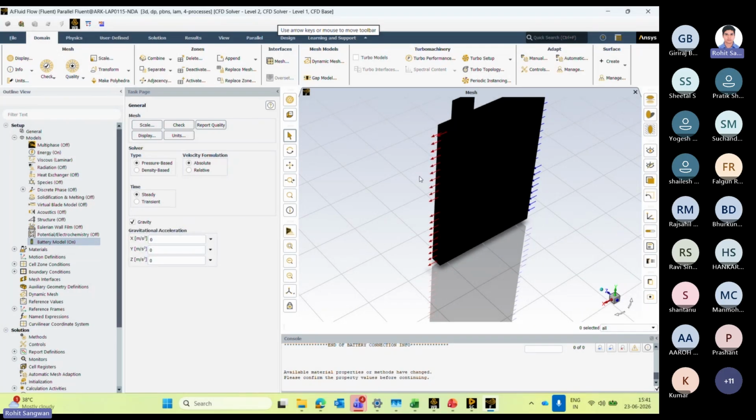But if there is a cooling channel path going up and down, like on the backside, then gravity will play an important role. So for the current case, if I am to define gravity, I can define the value, or I can define a function or expression, minus g. So we have two options. Minus g means the gravity value in the minus y direction, the downward direction.